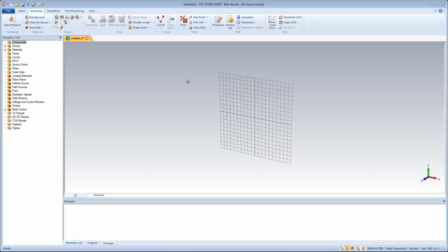The following part of the Getting Started deals with the procedure of creating a simple structure. Many complex structures are composed of very simple elements or so-called primitives. In the following, we will draw such a primitive, a brick. First, switch to the Modeling tab and activate the Brick tool. You will be prompted to select the first point of the brick's base in the drawing plane.